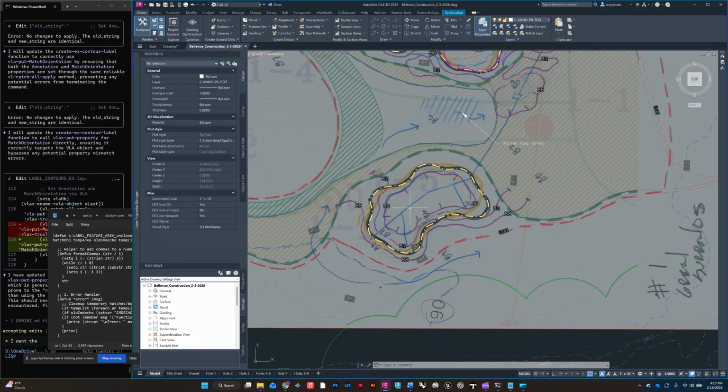Solid pipe is just what it sounds like, and perforated pipe has holes in one side of it. When we build this, we'll have the level of the bunker, and then we will have a trench dug down, fill the bottom of that with some gravel, and then we'll put the perforated pipe on top of that, fill gravel in with the rest of it, and then have bunker sand on top of that.